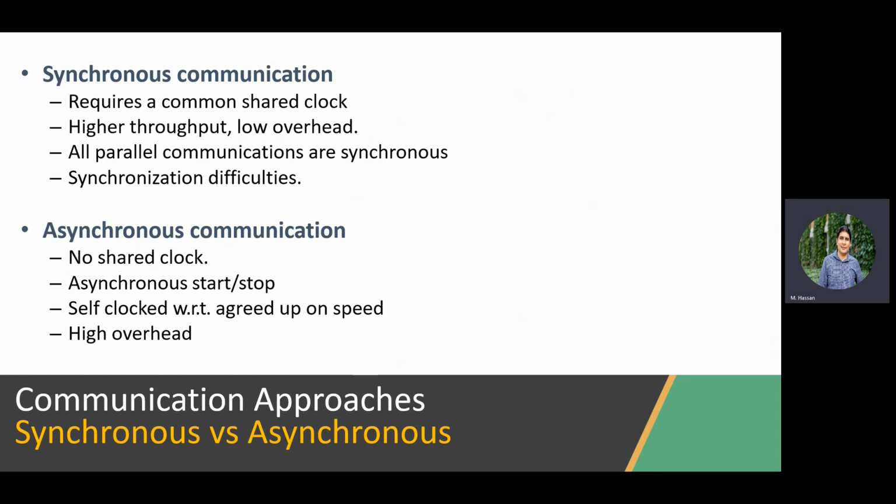In a parallel bus, how can you choose one wire to be the start? It makes no sense because all will arrive at the same time. So you will not know when to sample, but not because of the running speed, but because of the nature of parallel communication itself, right? So all the bits arrive together.